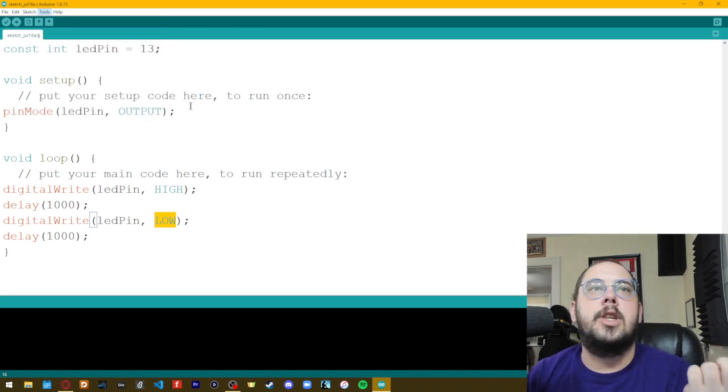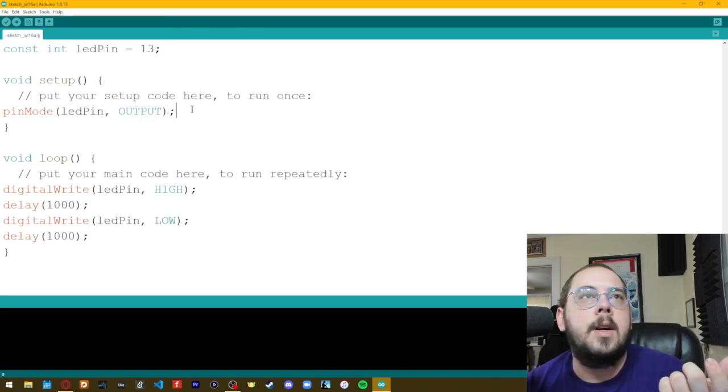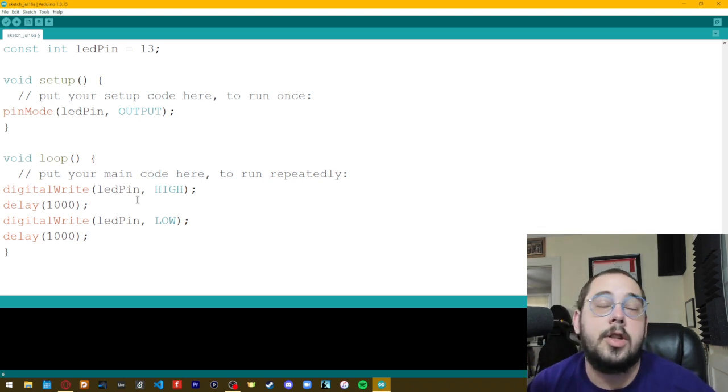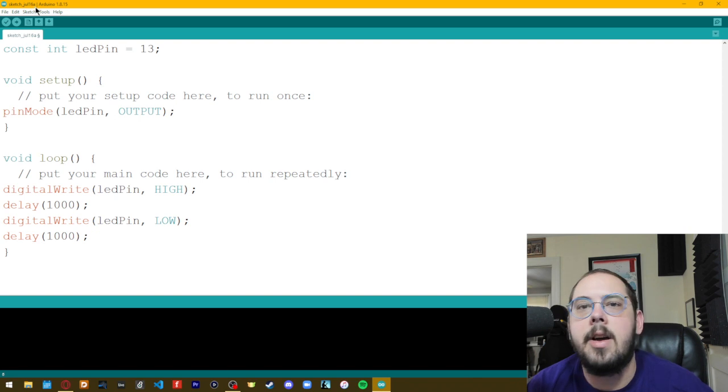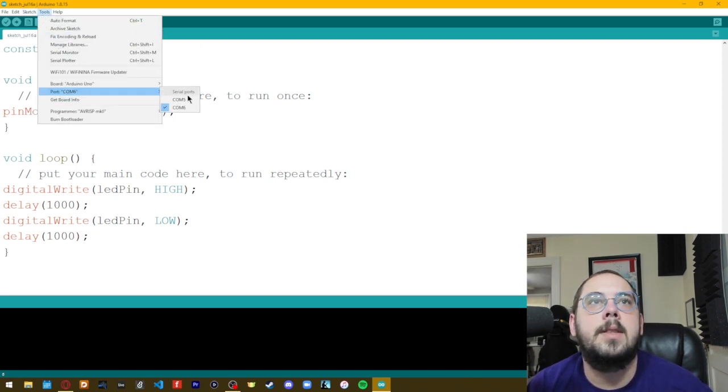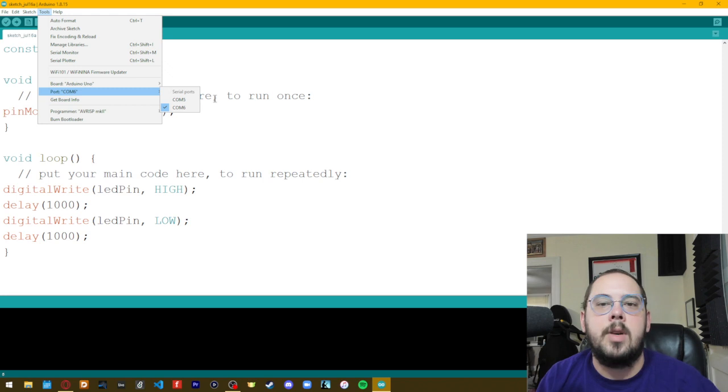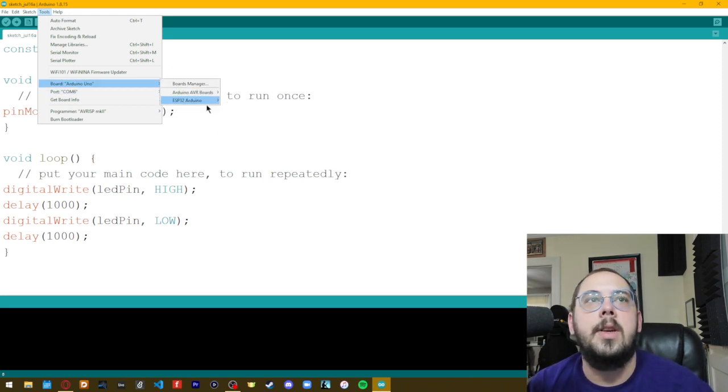As I'm recording just the code video, I don't have that right this second plugged in, but in just a moment we will. But anyways, you'll see that there. If you're on a Mac and not a Windows device, it won't say COM6. It'll have some big long name, but it'll still say in parentheses afterwards Arduino Uno, and that's the one you want to select.